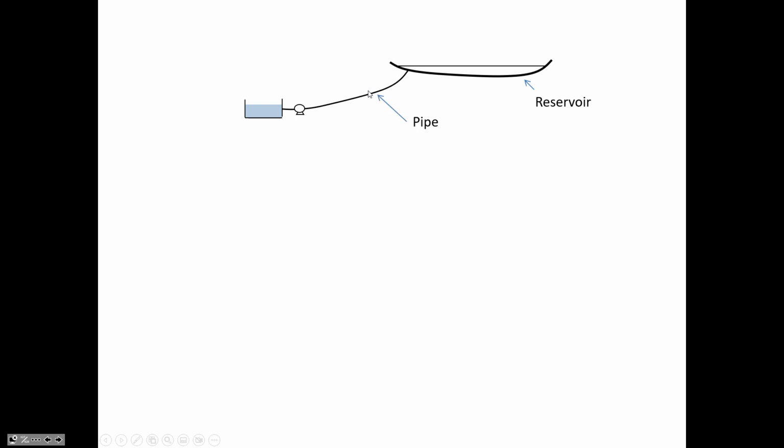So we've got a reservoir, water's flowing through a pipe, which causes resistance to flow. This is a pump at night lifting the water uphill. During the day, that's our turbine and power plant, which is generating electricity, and the water is flowing down to that lower reservoir. So you can calculate the flow of water. The flow rate is Q. Q is the flow rate. V is the velocity of the water through the pipe.